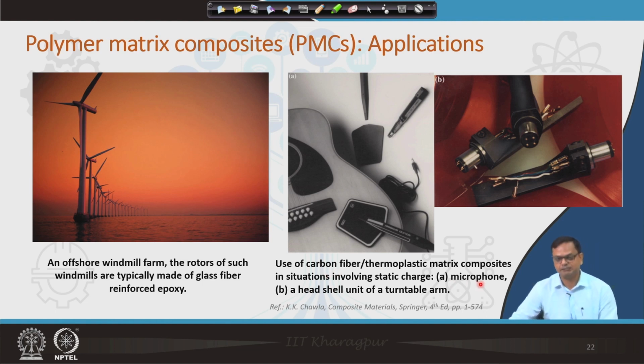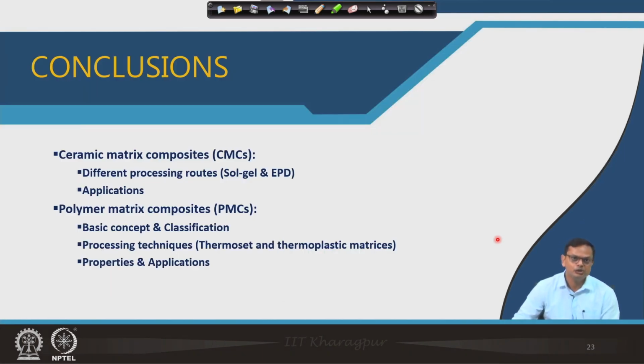Yes, for high temperature applications those are not good, you have to go to ceramics then, but otherwise if you need high specific strength, low weight and good fatigue resistance, then PMCs are definitely quite good alternatives. So with that I would like to conclude today's class.